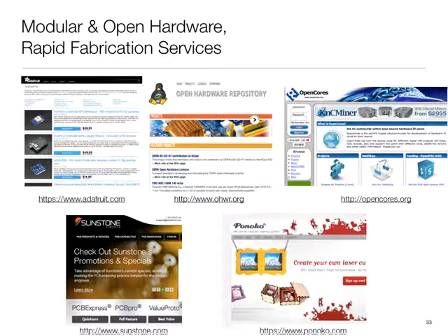But if we were to share, so instead of making a wafer which just has 100 copies of your chip, which would be very costly, we take 100 different designs from different customers and put them into a single wafer, then the non-recurring cost, the cost of preparing the chip mask and all, gets shared. Same thing with boards. Companies like Sunstone, that's the game they play.